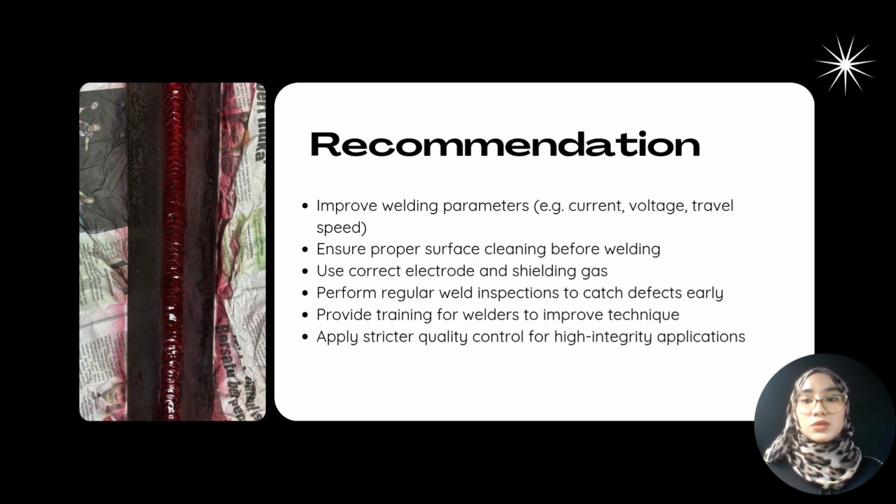Regular inspections should also be carried out to detect any defects early before they become critical. Lastly, for applications that require higher structural integrity, stricter quality control measures should be applied to meet higher standard levels such as ISO 5817 Quality Level B.